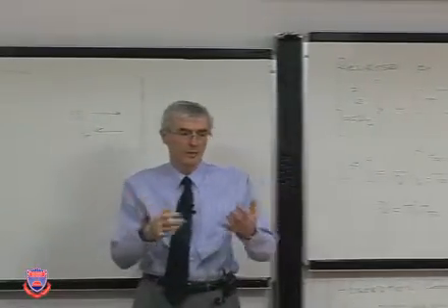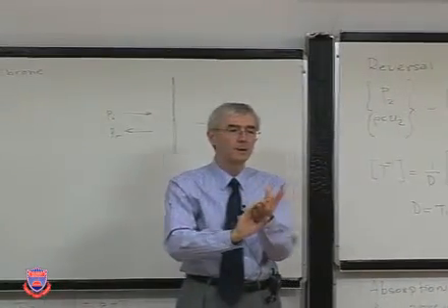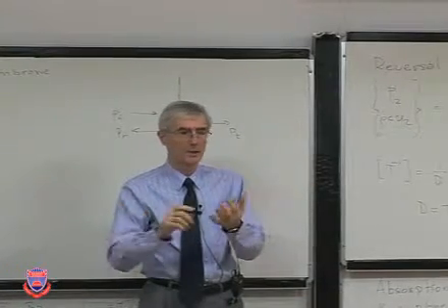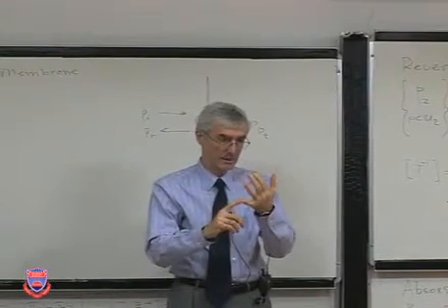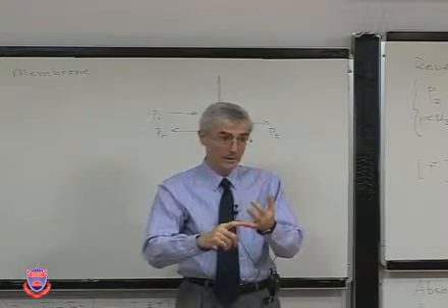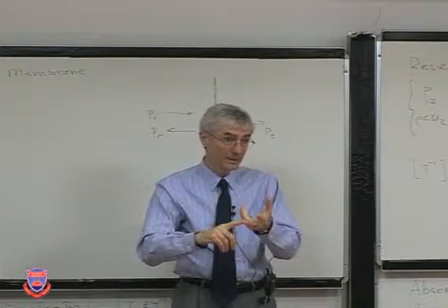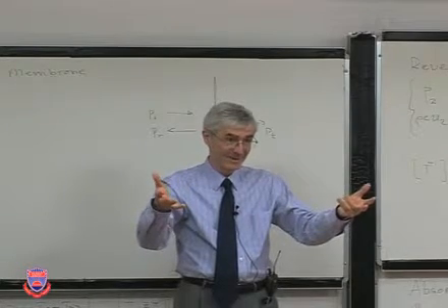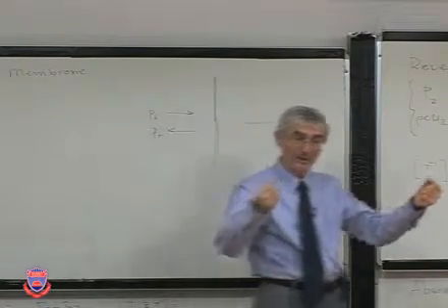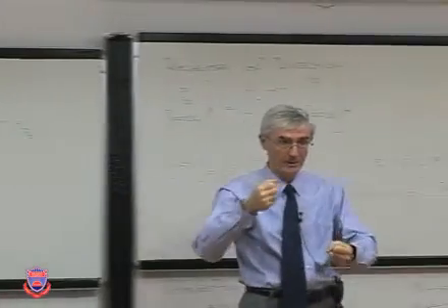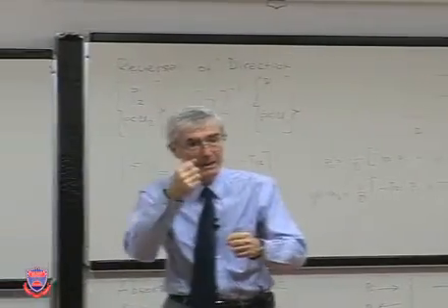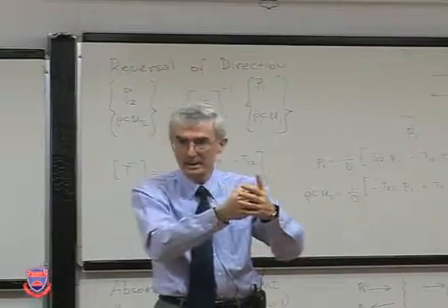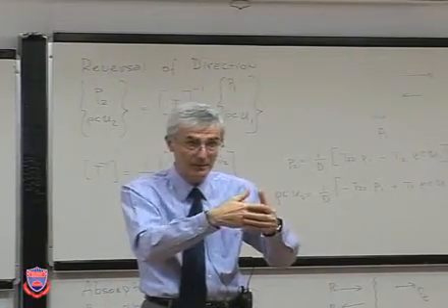So, when you think about the impedance of a physical object, you have what? Mass. Stiffness. Come on. What's an impedance? Force divided by velocity, okay? What are impeding the force from gaining velocity? It's mass, you have to push it. It's stiffness, same thing.